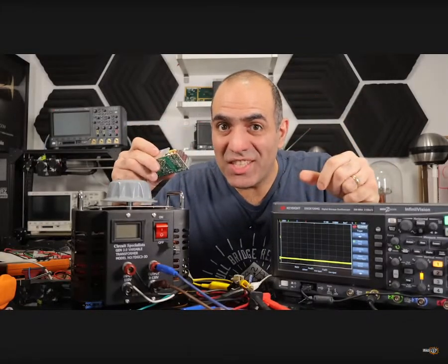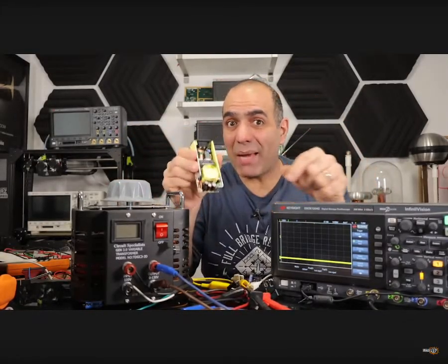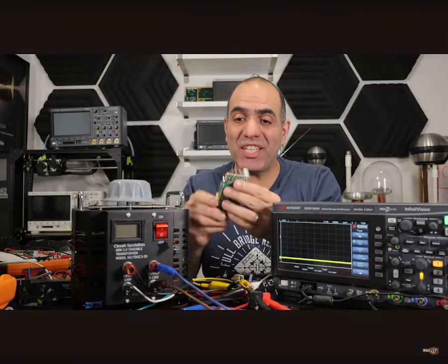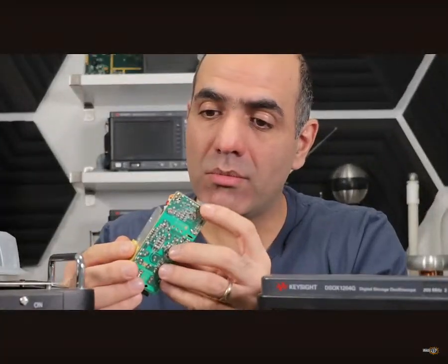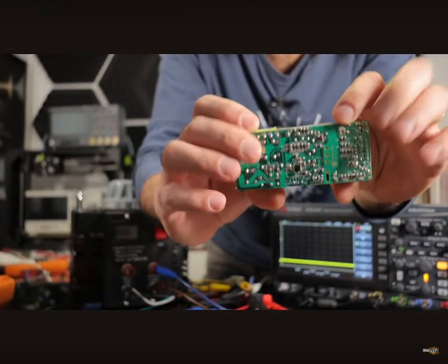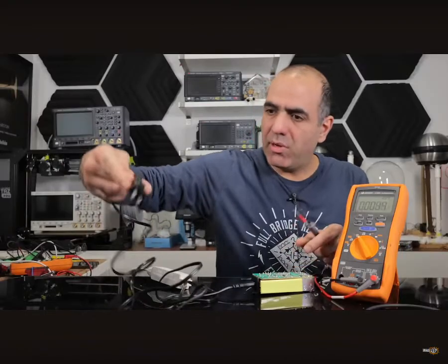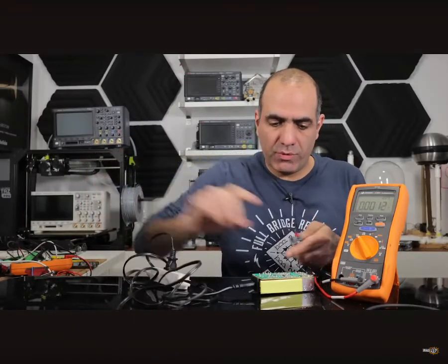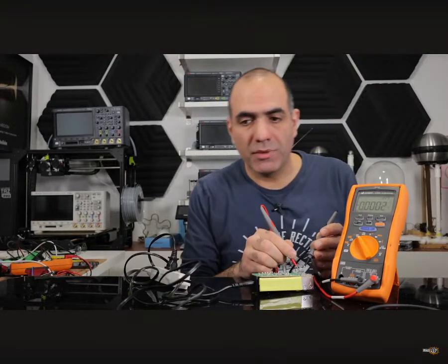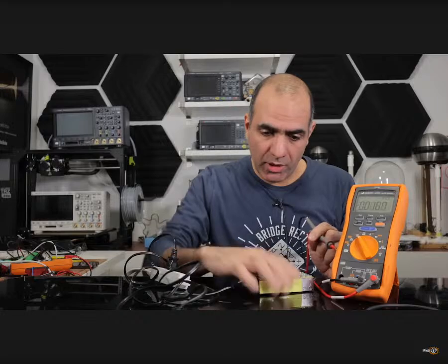Now that we know all this, let's repair a broken power adapter together. This also doesn't output voltage. Looking at the circuit capacitors, they all look fine. So I guess we are stuck with 100 other possibilities. Let's plug it in and measure the output voltage. There is nothing. Is there a burn mark on this?